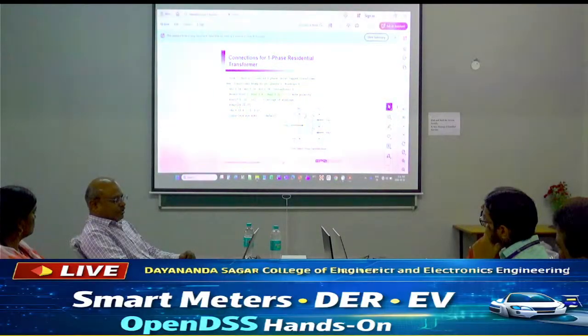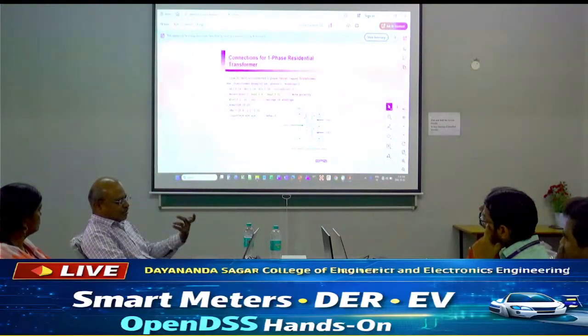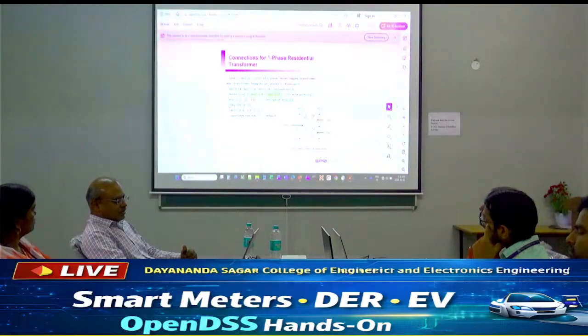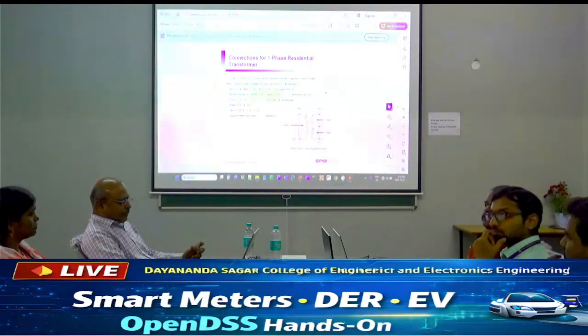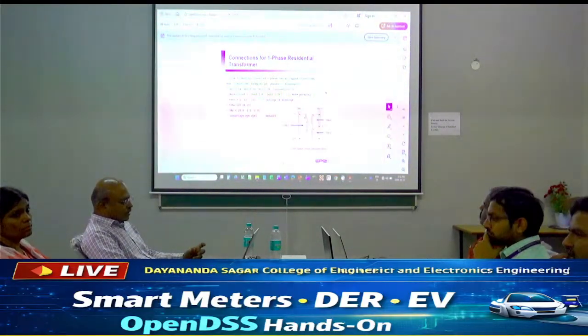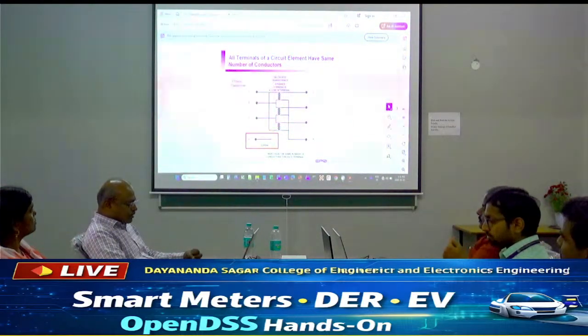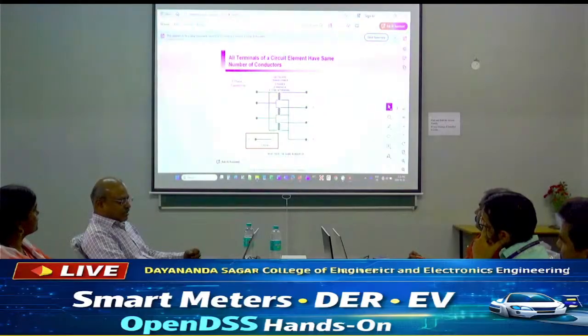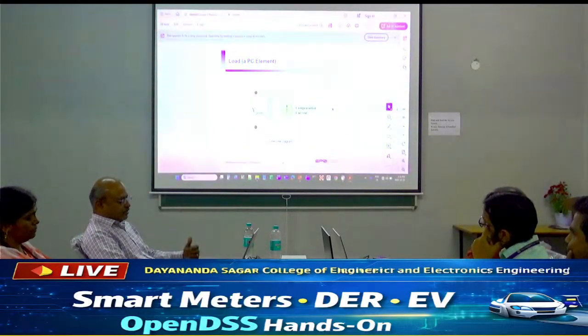KVA is the same, like 25, 25, 25 therefore. And percentage R's, so basically the losses and all those things will be there, and it is a Y on all sides. So if you have a delta Y, then you have to say delta and then Y, so you can mention. So okay, this is a three-phase transformer, and it's a delta Y three-phase transformer, right? So this side is a delta, this side is a Y. So you can define those kinds of things.